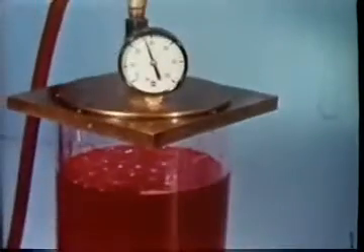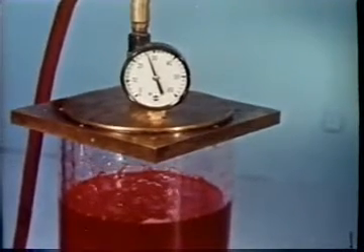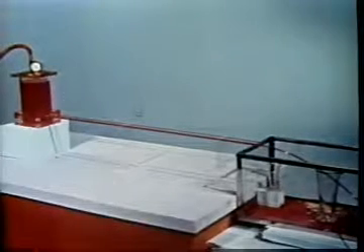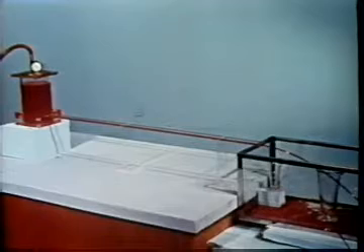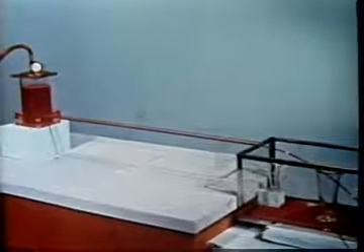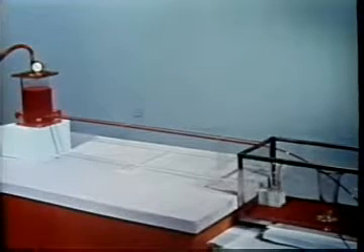Here the tangential stress due to viscosity is balanced only by the driving pressure. Though the Reynolds number is not necessarily small, there is no change in the inertia of the flow as it passes through the tube, so that the results of calculations of the kind used in thinking about low Reynolds number flow are applicable.